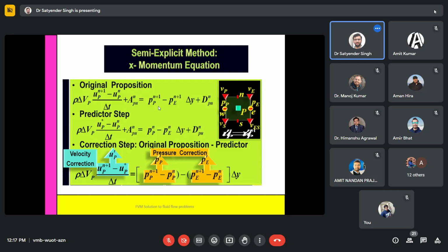It means that at that wall, the value calculated inside, just at the border node, has to be assigned to the boundary node, because there is no reference of the pressure at the boundary. We are unknown with the pressure value at the boundaries, except p equal to 0 at the outlet boundary.